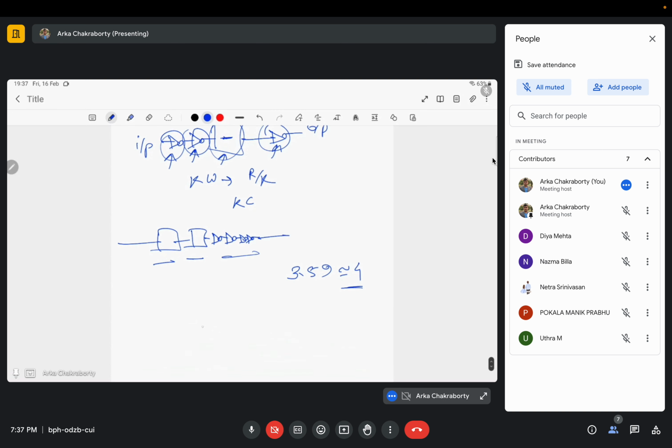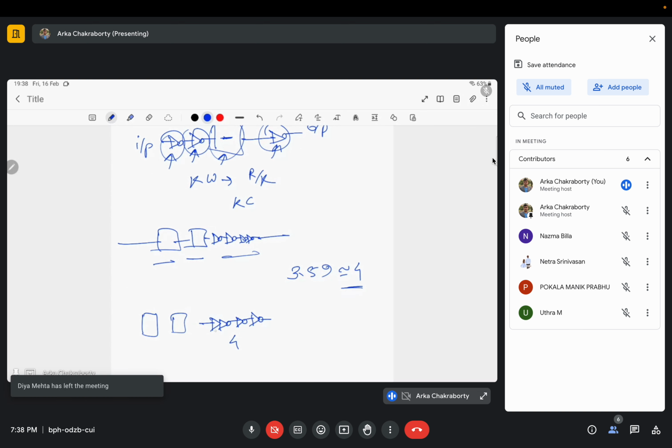So if you are given a number of circuits and you want to further optimize the delay, we add a buffer chain or inverter chain in a factor of 4. That is, we will either be inserting 4 inverters, or 8 inverters, or 12 inverters, or 16 inverters, in such a way. When we solve that minimum delay problem, find the derivative and the solution, we get this result. From here this number 4 is coming.